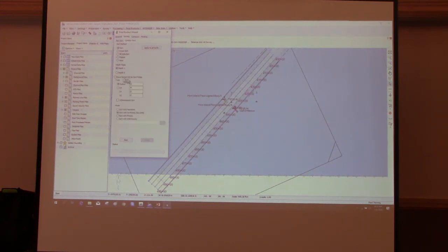So right now I'll use sort, we'll use depth 1, I'll leave a radius of, I'll do 50 in here. Okay. No, actually, for the contours I might want to do something like maybe a 10-foot sort or something, so I'll get a bit more accurate contours. But for the plot, I might want to use the sort program and plot at 50-foot intervals. And then I have the option here, sort with no priority.